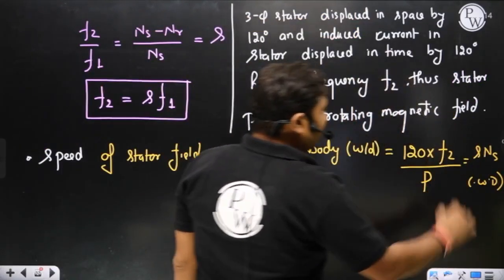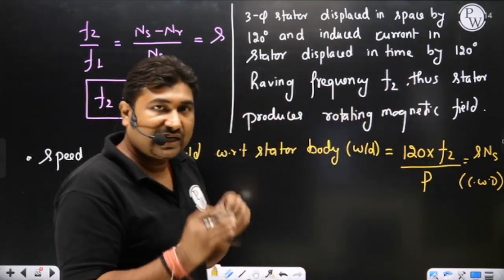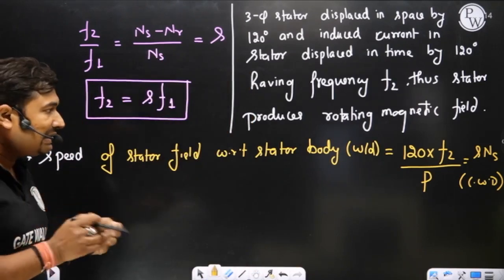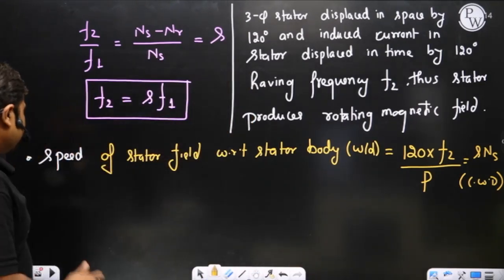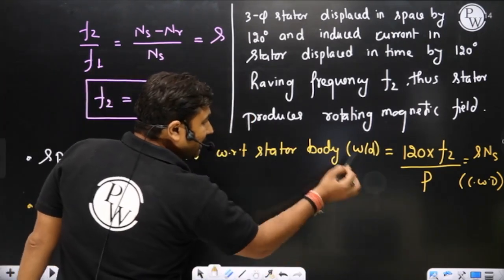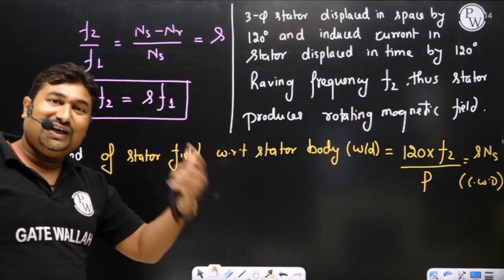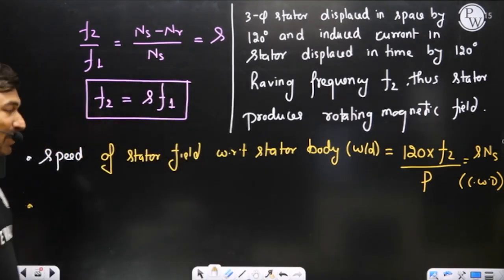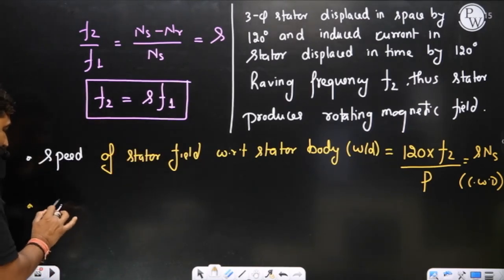Is it okay? Yes, sir. The rotor field is rotating in a clockwise direction. The rotor is rotating in an anti-clockwise direction. The stator field is also rotating in a clockwise direction only, because the phase sequence of induced EMF in the stator is the same as the direction of rotation of the rotor field. Hoping up to this part everything is clear. Great, sir. Now please observe.